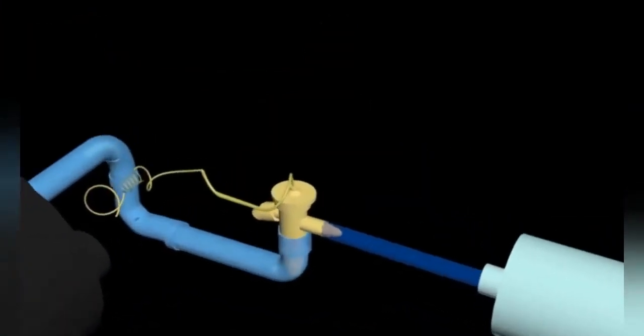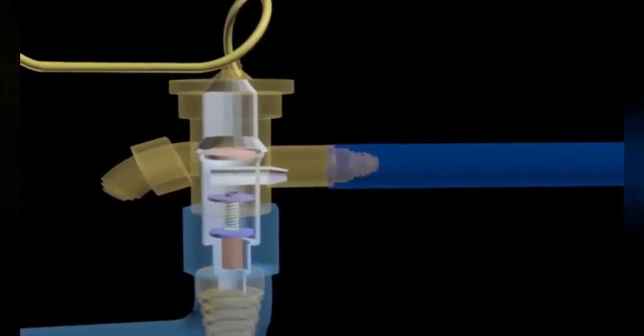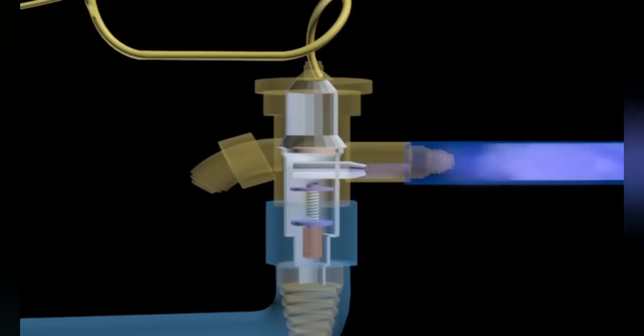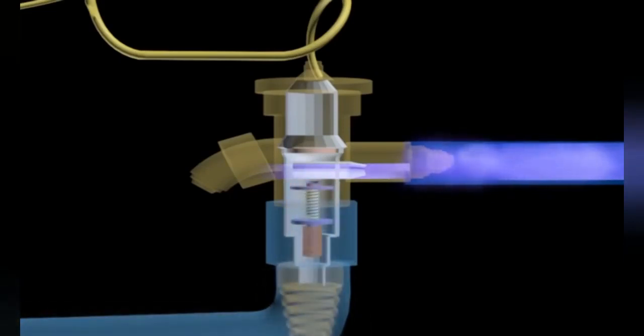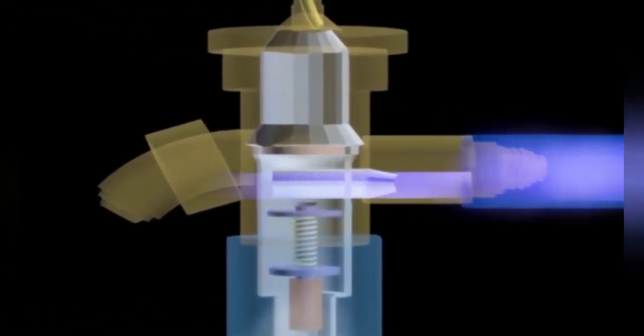Expansion valve. The expansion valve serves to reduce the pressure and control the flow of refrigerant going into the evaporator. When the pressure of the refrigerant has declined drastically, the temperature will drop dramatically, which is lower than the chilled water temperature. In a centralized system, the expansion device used is the TXV, thermal expansion valve type.